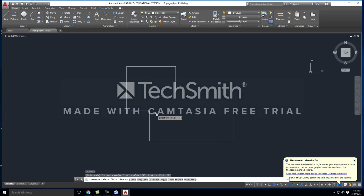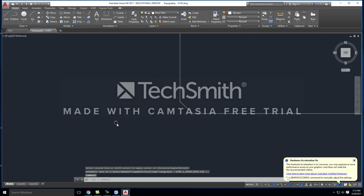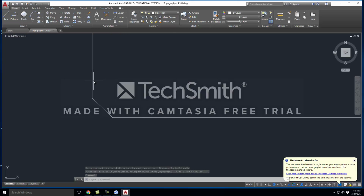Okay. Just like we did for fillet when we clicked on R for radius, instead of hitting R, you're going to hit D for distance. All right, and we'll make something like 6 feet. Okay, specify second chamfer distance. I'm going to make that the same thing, and now I will select both my first and my second line. Okay, so now notice that I have a nice chamfered corner.